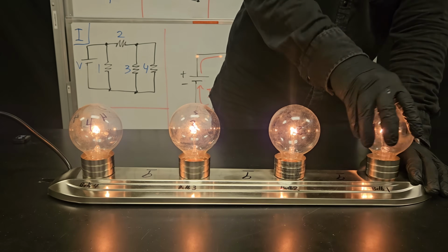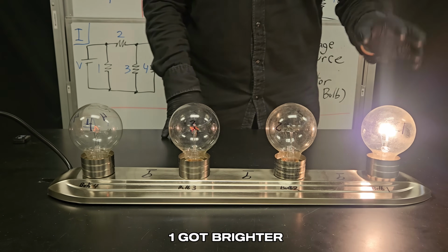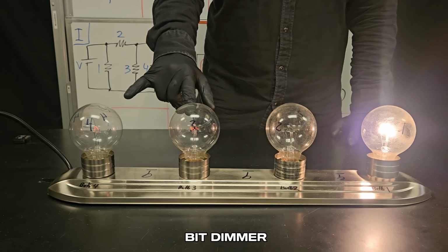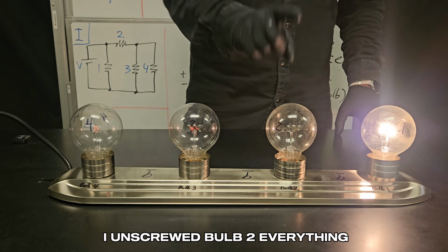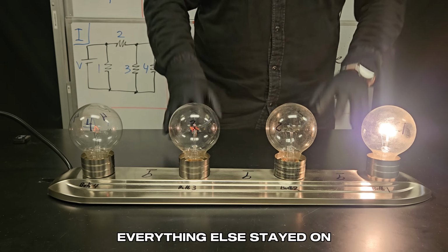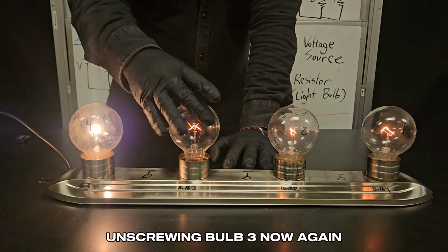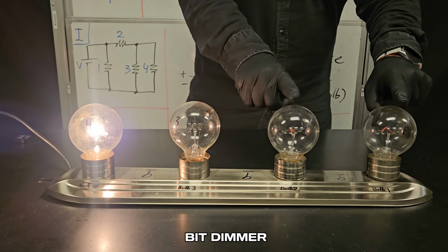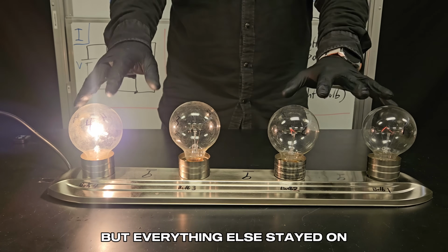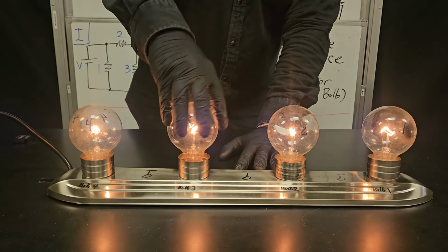Okay, let's unscrew bulb number 2 now. Again, bulb 1 got brighter. Looks like 3 and 4 got a little bit dimmer, but none of them went out. So when I unscrewed bulb 2, everything else stayed on. Unscrewing bulb 3 now. Again, same thing happened, but this time 4 got brighter, and it looks like these got a little bit dimmer, but everything else stayed on. So when I unscrewed bulb 3, nothing went out.